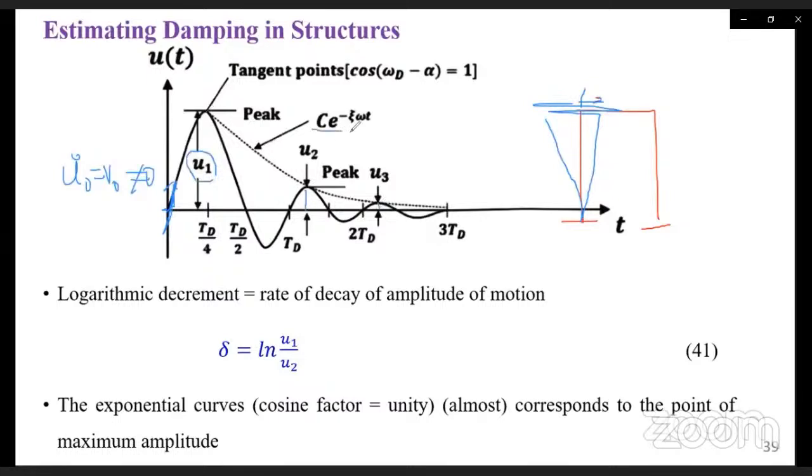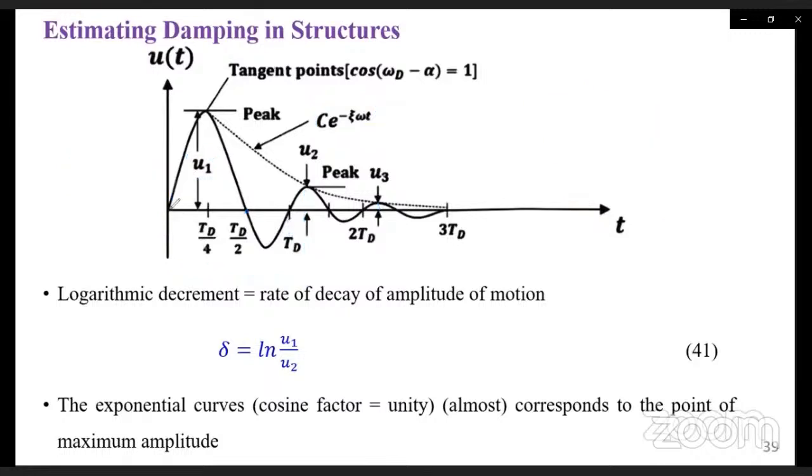And we are seeing this exponential decay of our amplitude. And of course, we can see the damping, the peak occurs first at a quarter of the damped period. At a half, we have the first half cycle, and until we have the full period here at the full cycle. Because as you can see, the motion starts here. So this is where you have the full cycle.